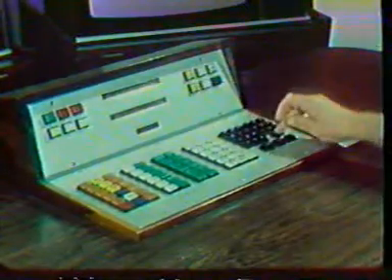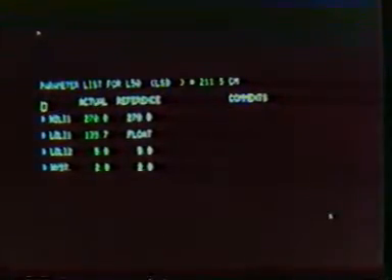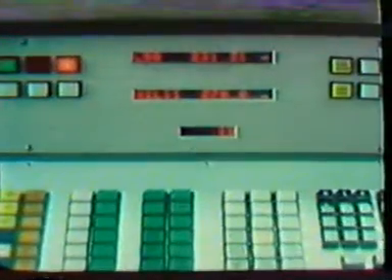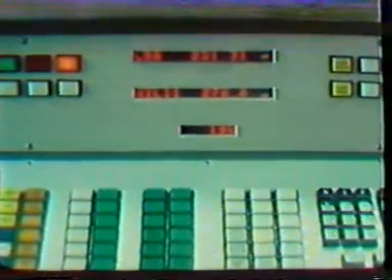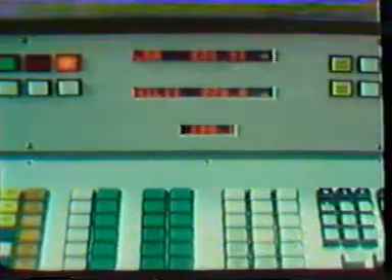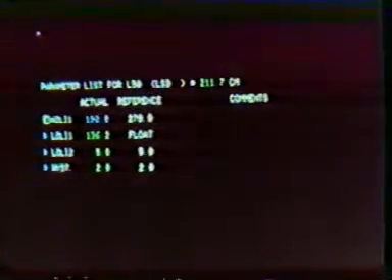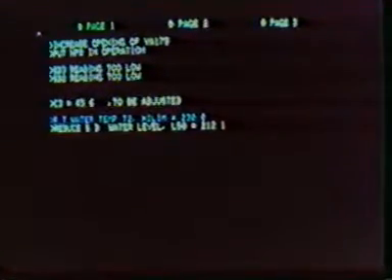The maximum amount of process information which can be given simultaneously to the operator is much less in the CRT display-based control room than in the conventional control room. Therefore, an effective plant disturbance analysis system which checks input signals against limits and based on plant status selects proper messages for display is highly desirable. The operator can, by means of the tracker ball and the console, change the monitoring limits. This is visualized with the help of a display for each monitored variable.